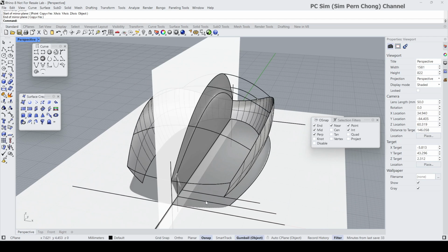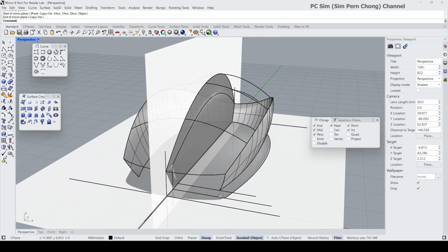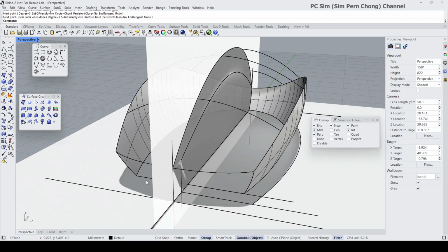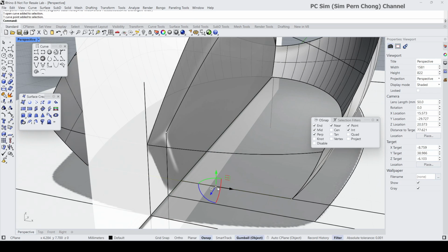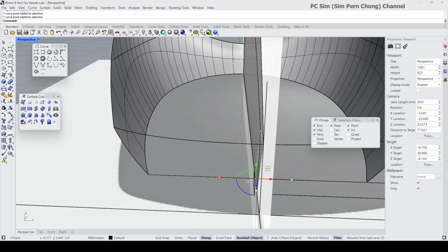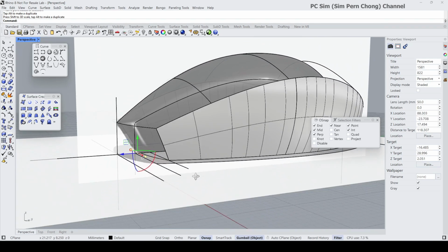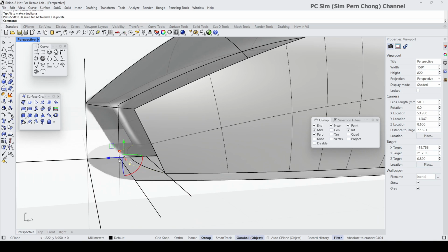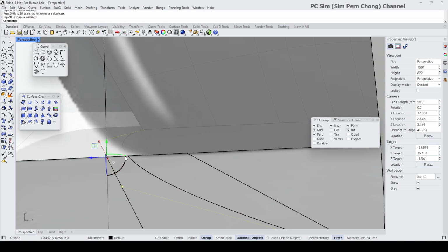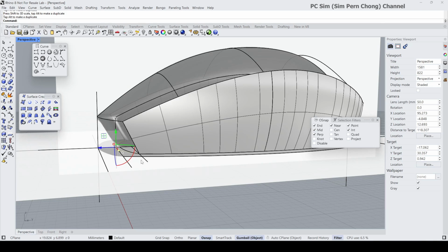Okay, so I don't know what the base looks like over here, so I'm going to do a little bit of an informed guess again. I'm going to use this interpolate point, snap to here, snap to here, select these points, drag out, and I want maybe something like that. Make sure that this end is more or less corresponding. We're going to do a fillet here, so most probably you end up here, then we're going to round off. As you can see, I'm moving it slightly forward because later we're going to do a fillet or round over here. Okay, something like that.